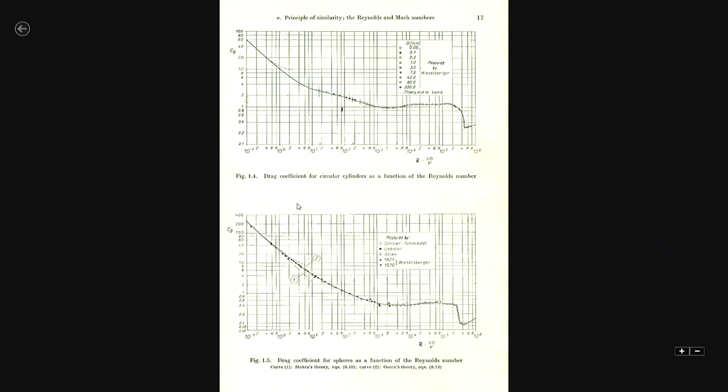So, you remember the particle tracking experiment we talked about long ago. You drop a small particle through a column of oil, let it accelerate and attain terminal velocity. Under terminal velocity, this is called gravitational weighing, because that weight and drag will balance each other and acceleration becomes 0. So, then you can say that the drag is balanced by weight. And you know the weight, effective weight, that means mg minus buoyancy. So, that is a method of weighing.